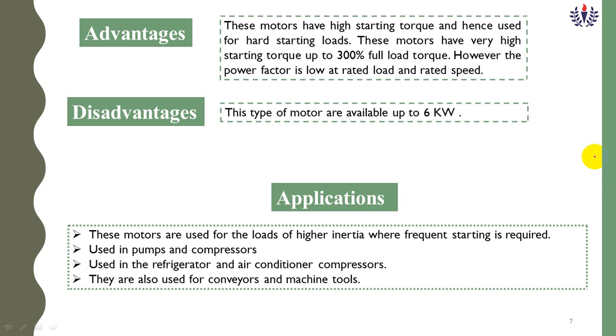This motor operates with high loads, right? So based upon the high load, the capacity, that is the specification of the capacitor, also has to be identified. We have to take care of the capacitor, because capacitors are a very dangerous part. If we operate at a high current or high voltage greater than the rated specification of the capacitor, it will automatically blast. It will be an accident, so we should take care.